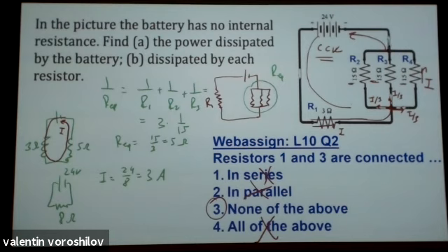And what can I calculate? Voltages. For example, this voltage, delta V1, should be equal to current and resistance. So current, which is traveling through this resistor, 3 amps, times the resistance 3 ohms, 9 volts.